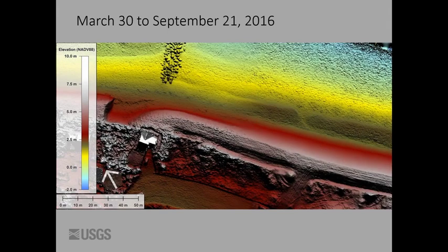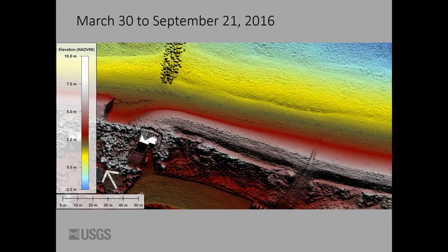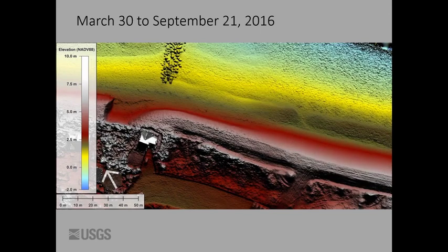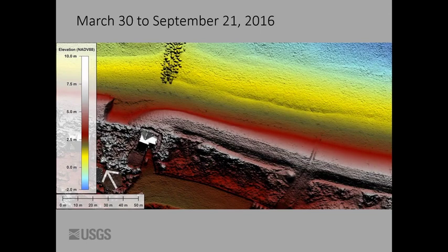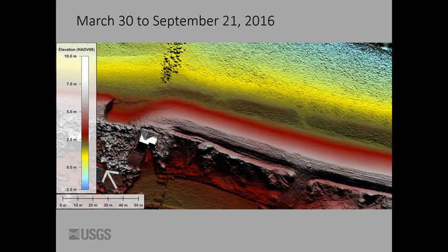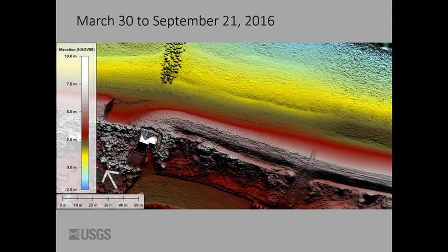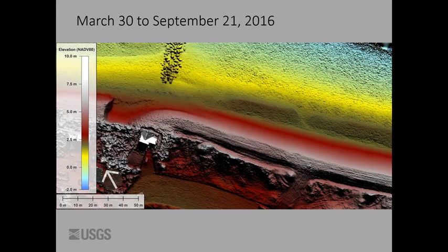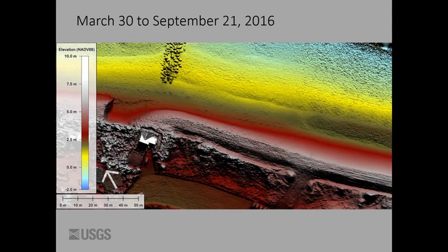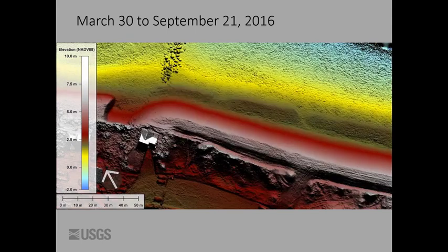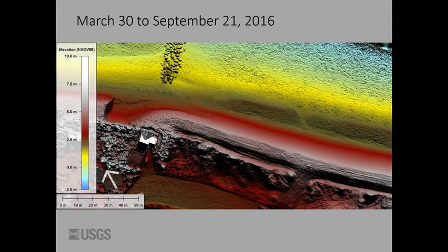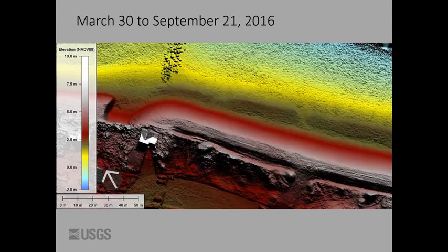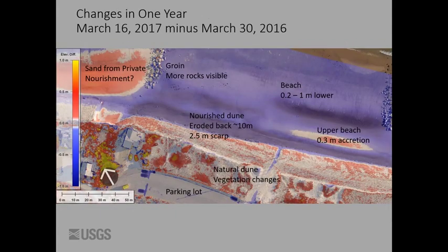Vegetation is handled, most of you probably know this, in LiDAR. Basically, they figured that the farthest point is looking through the vegetation and might have found the ground. And so they use geometry. Not as many points from structure from motion get through. We don't get as many points as you would with a LiDAR cloud, so that doesn't work quite as well because not as many get through. But we also have color. So green might be leaves and brown might be ground. There's ways to start teasing that out.